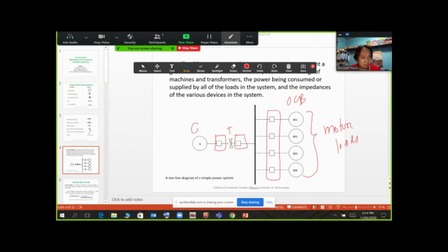incorporated there. For example, you have types of relay, and an overcurrent relay is also different from a frequency relay, which is also different from a power relay. It needs the device numbers, etc. So the fuses are different, the isolator switches. So in our modeling of a certain equipment, or rather a certain power system, we will just draw the power system in a much simpler way. So sometimes we eliminate the protective devices. We just draw it in a line instead of having all of the protective devices incorporated on the power system.